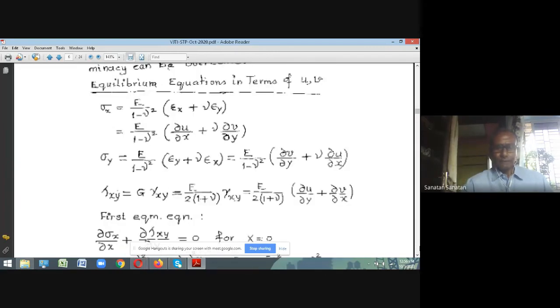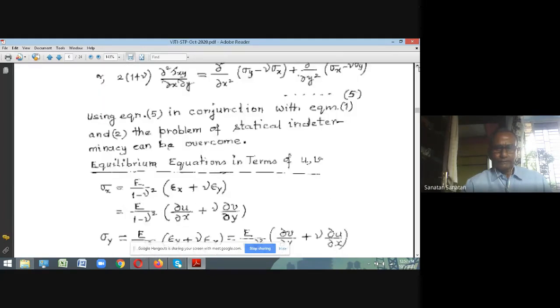So if you make use of the compatibility conditions, you get the exact equation to get over the statical indeterminacy. Now I want to tell you one more thing about the compatibility condition in the case of strength of material. When we wrote it in terms of displacement, we had U1 equal to U2. So there was actually one extra equation, which, when we wrote it in terms of the end forces, was giving linkage between the two end reactions. We will try to do the same thing here.